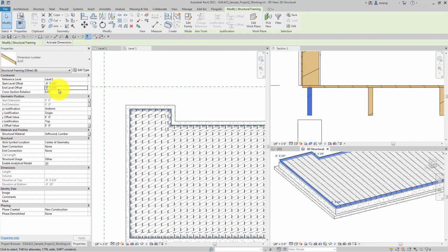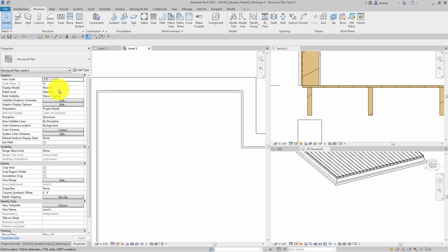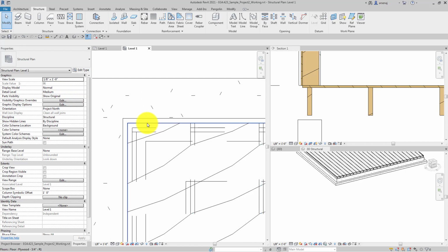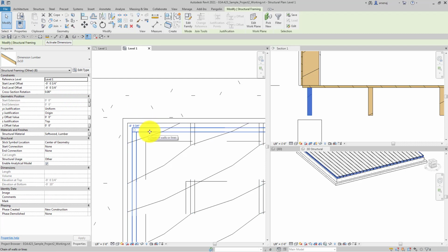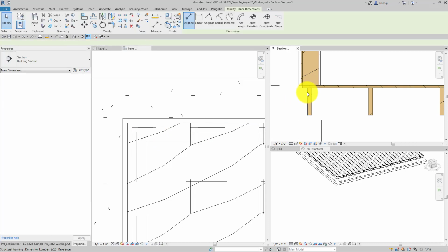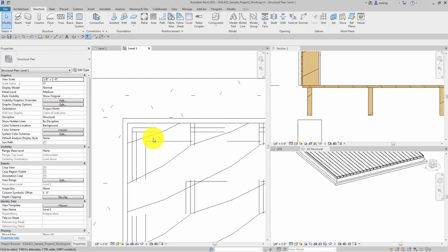And right now it's centered on this wall above, and I think the best way to go about changing that would be to offset. So instead of having to go and align or move all the beams to this edge here, we can offset all of the beams. So let's get a dimension that we'll need to offset, 1 5/8.